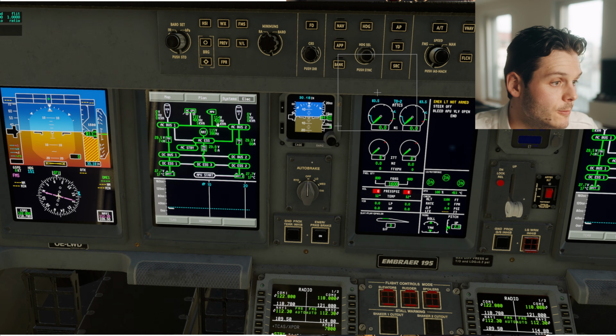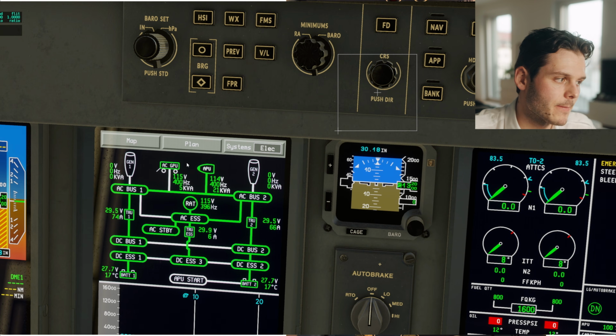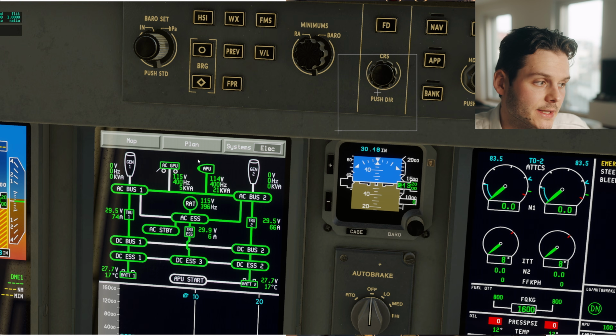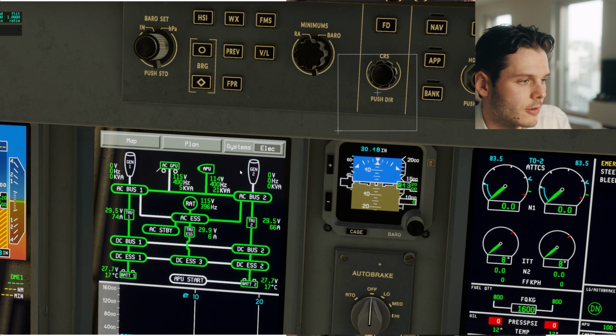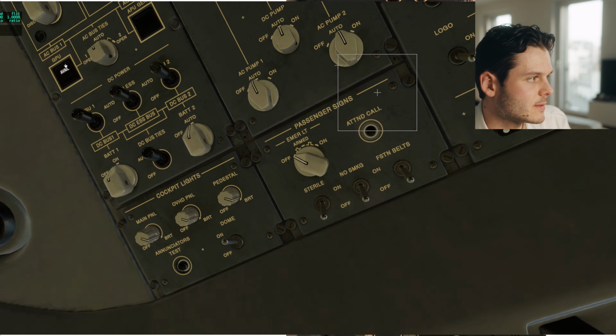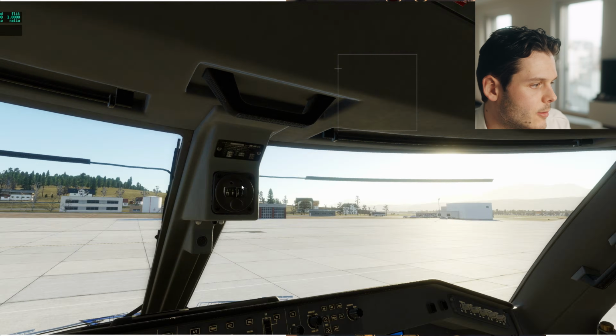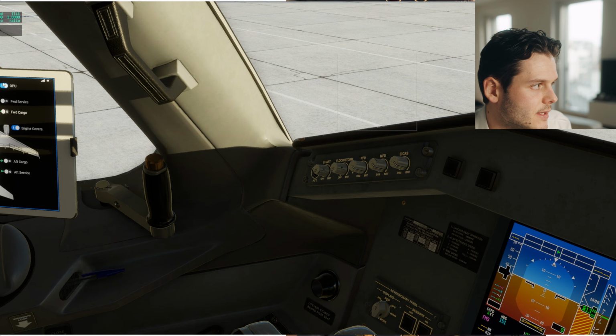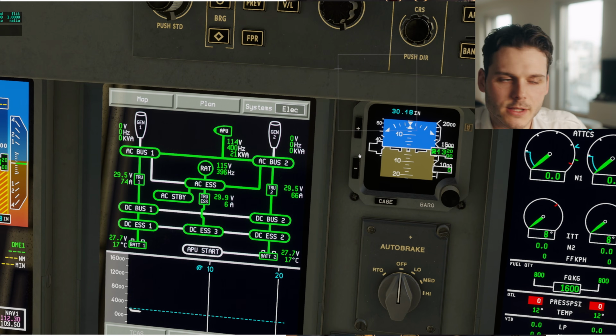Now we have the APU, and another interesting fact, the logic of the aircraft is if there are engine generators available, the aircraft will be powered by the engine generators, if both are available. If there is an APU available, it will be powered by the APU generator, and if there's only AC available, obviously powered by the AC ground power unit. So let's switch off this button. There we go, and now we have power from the APU. We can disconnect the ground power. This is how it works, basically.